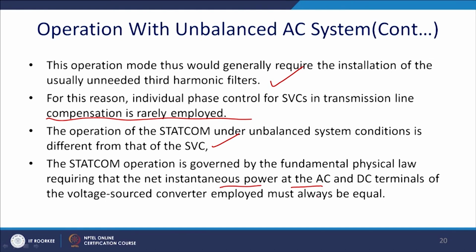Please note that point. The operation of the STATCOM under unbalanced condition is different from SVC. The STATCOM operation is governed by the fundamental physical law requiring that the net instantaneous power at the AC and the DC terminal of the voltage source converter must always be equal. Thus, you can have unbalanced power or balanced power, it does not matter. So, it can better handle the unbalance.